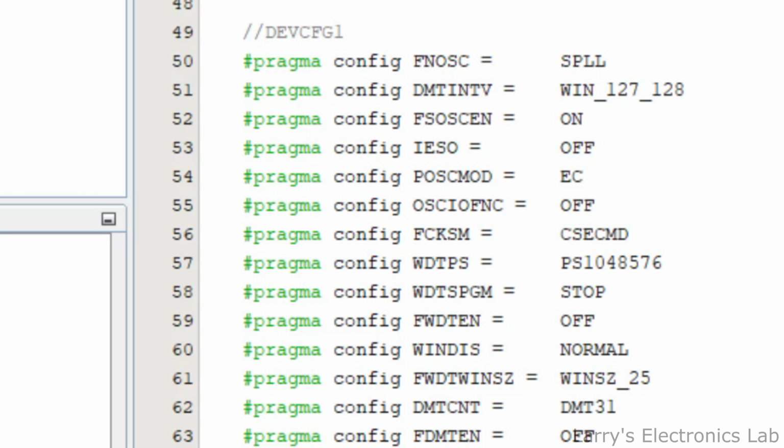If you don't have one, then this must be disabled, probably because the input would be floating and it might cause it to oscillate. I'm not sure, but they say you shouldn't enable it if there's no oscillator on there. I do use the oscillator for a real-time clock on mainbrain, so this enables it right after reset when the system starts up.